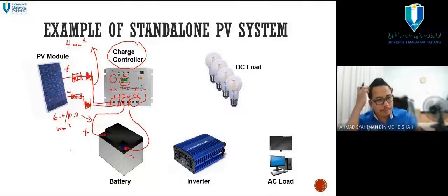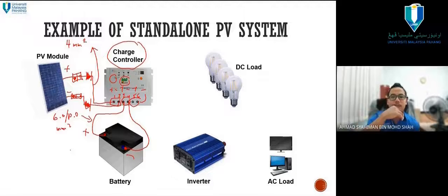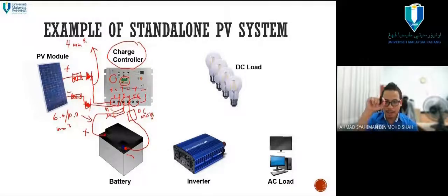Untuk battery cable. Okay, wire untuk cable untuk battery. Alright. Then also again, here you need to letak MCB, not the fuse, but you put the DC MCB, miniature circuit breaker. DC MCB, both plus and minus. If you don't have the DC MCB, you can put the AC MCB, but maybe if something happens, it will not trip. DC dia akan trip dengan DC. But okay lah, at least kita boleh switch on off, in case.